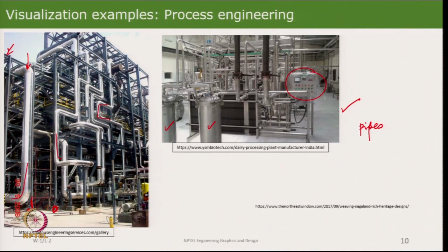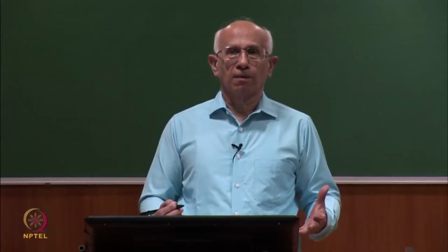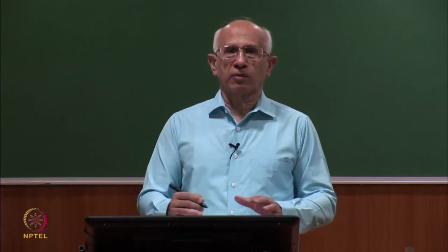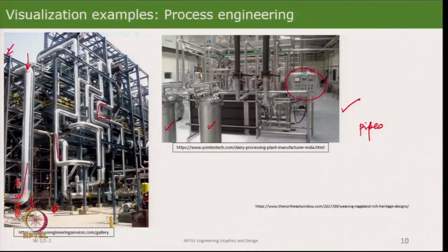So, one designs what you want to do, how you are going to place it horizontally and vertically, and then decide how the connections have to be made, find out how you are going to support the whole thing, work backwards and say, well, does the support interfere with the piping and the layout, iterate and freeze the design.